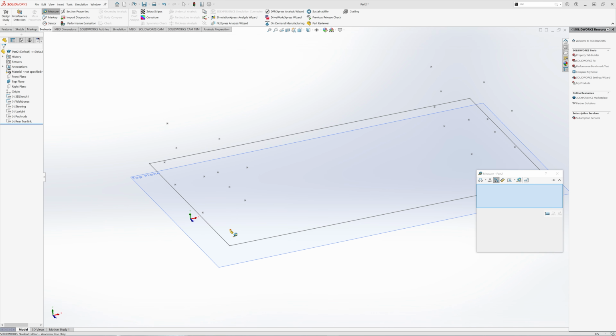Another important aspect of this workflow is how it supports teams that carry the same upright design from year to year. As long as the team knows the dimension that defines the kingpin axis, that value can be input directly into the software. And the distance generated in CAD will be exactly that dimension. This means there's no need to completely redesign the uprights each season.